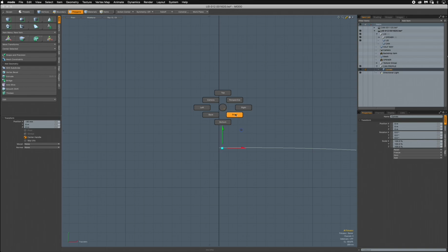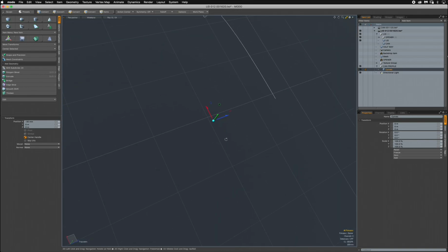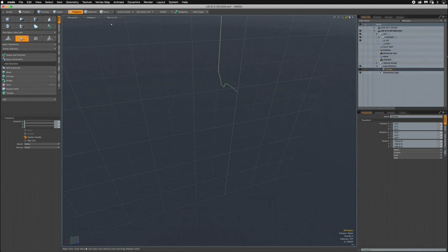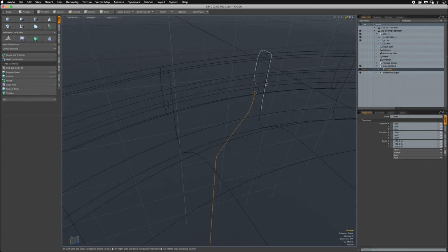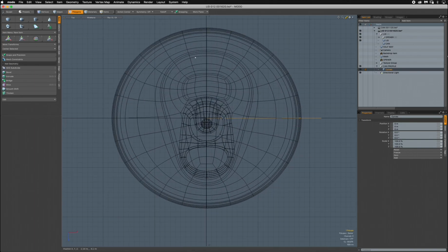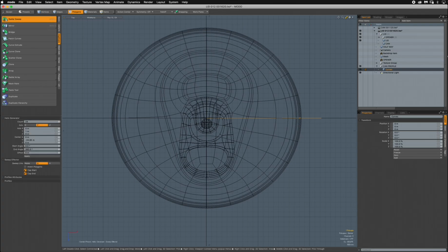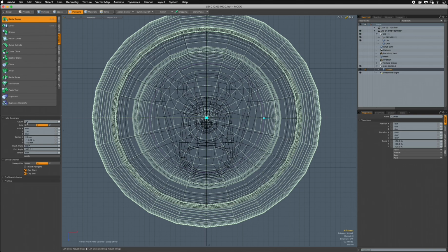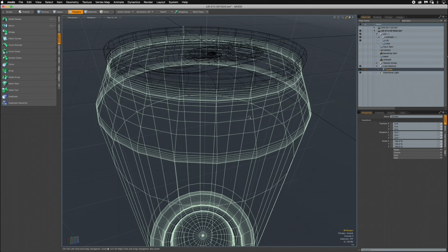Before we go to the top view, let's go perspective, look around. Just select this edge. There's another little piece that I brought in here. That's just for reference. Just select the can itself. We go to the top view. We're going to do a sweep. We're going to go into duplicate, radial sweep. So click right in the middle. Make sure it's set to 24, space bar, and you should be in good shape.